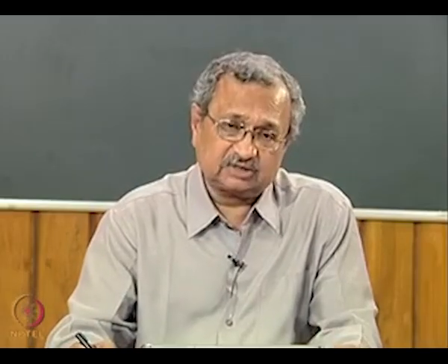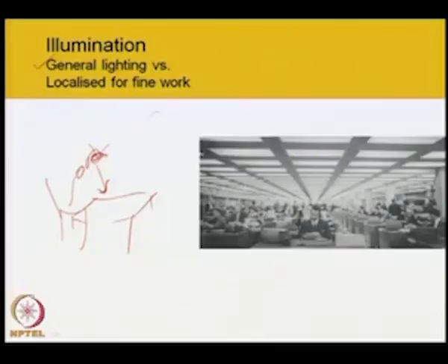Normally, what happens? Yes, an incandescent lamp provides shadow. Now, whether the shadow is necessary to complete the task or not. Like when we see a meter reading, the needle and its shadow should match together to give a proper reading. In such cases, the shadow is necessary. But when we require even lighting that is still localized, there the diffused lamp system should be better.